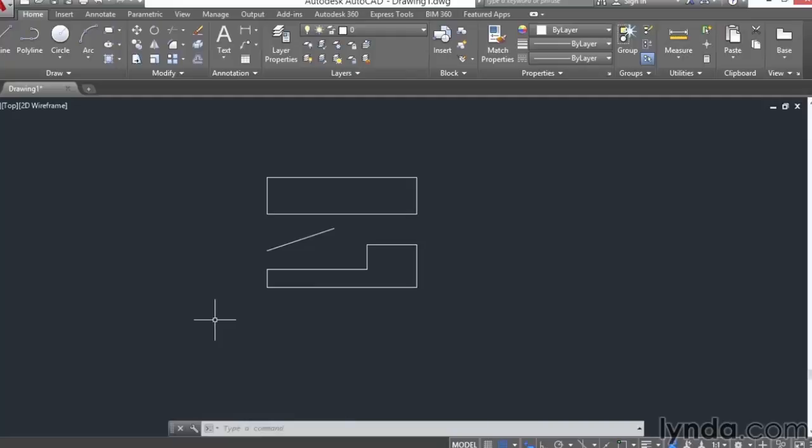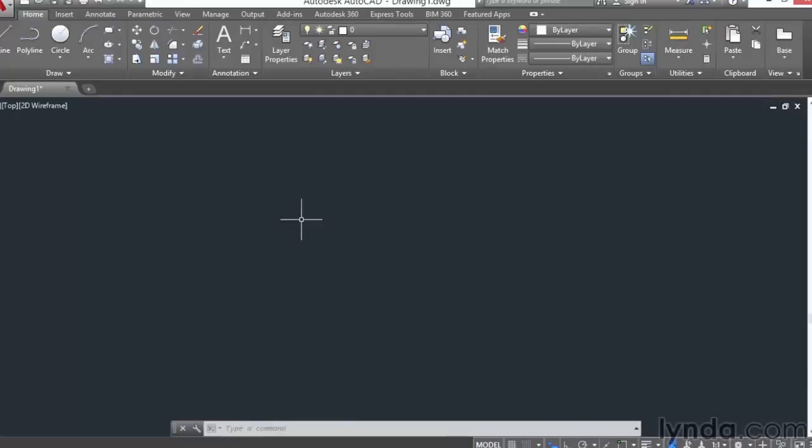to a spatial grid. In this video, we'll create an isometric drawing. Isometric drawings are two-dimensional illusions that represent three-dimensional objects, but they're not truly 3D models. This is perfect for AutoCAD LT, which doesn't support 3D modeling. You can actually represent a 3D object in isometric.